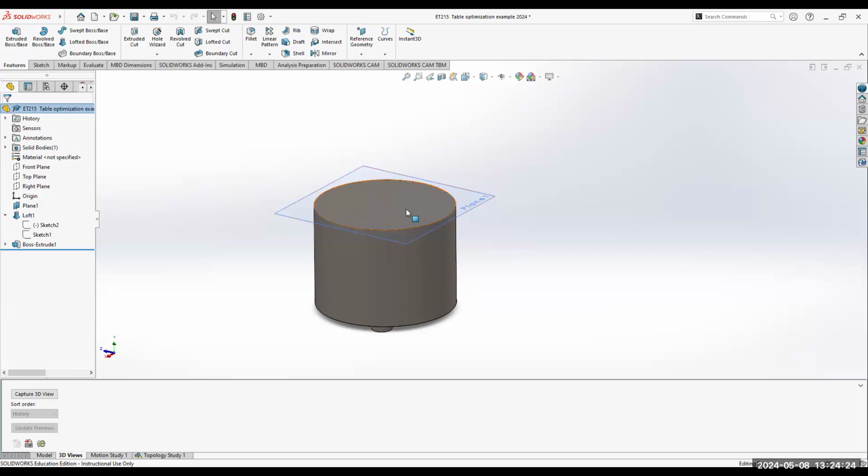And I put a distributed load on top, right? And this is what it gave me. And I printed it this morning, right? Cool. So that's an optimized table that uses SolidWorks artificial intelligence for finite element analysis to determine where the stress paths are. These are the regions that I preserved, those rounds. And wherever the load goes, it automatically preserves. You don't have to preserve that.